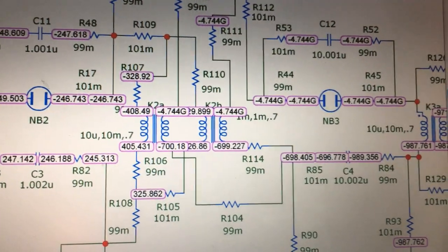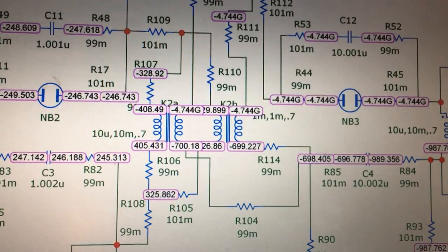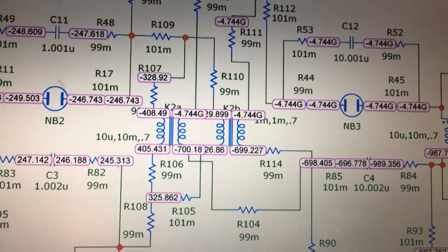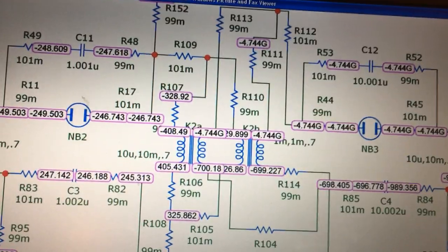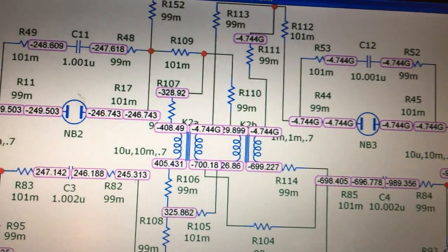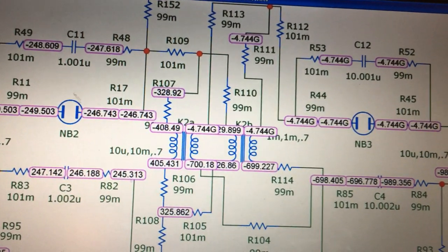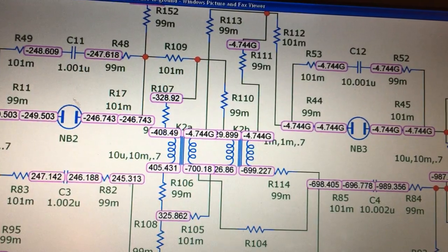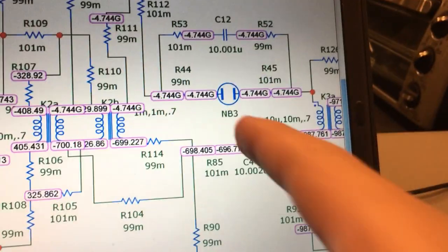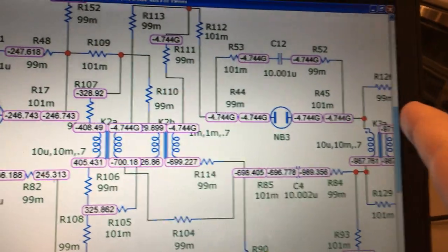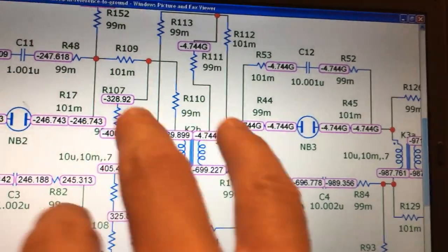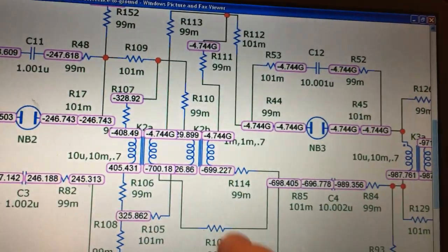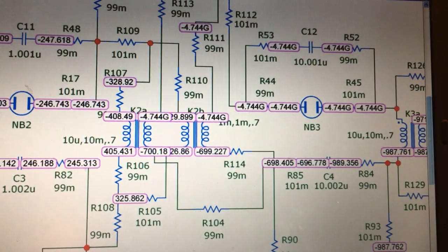I don't have to fine-tune this because this is just a simulation to make sure I know what I'm dealing with. If I was building this in the real world, I would start with a small circuit, and then gradually each model would be slightly larger in capacitance and inductance, still keeping the same frequency of the sine wave input. Just increase the capacitances and inductances to increase my power level.